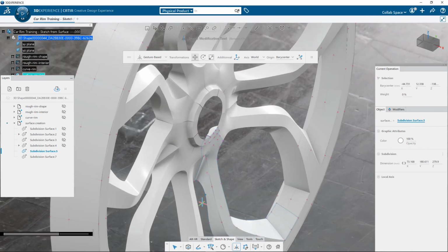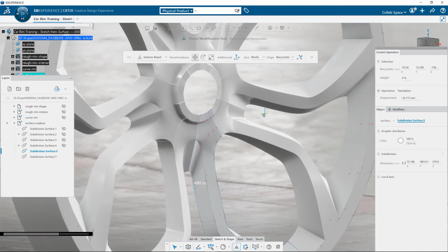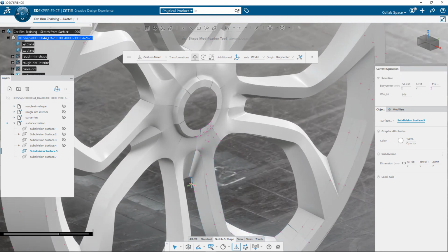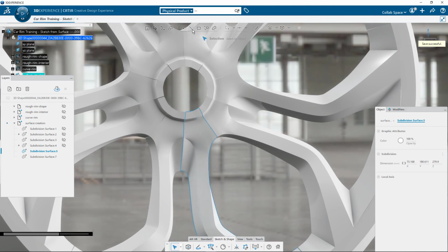With the snapping between vertices, I clean also the base mesh. I activate it by pressing the Shift key while I am moving with the gesture based on one direction. You see that the cursor takes the shape of a little target to select the snapping target in the 3D view.